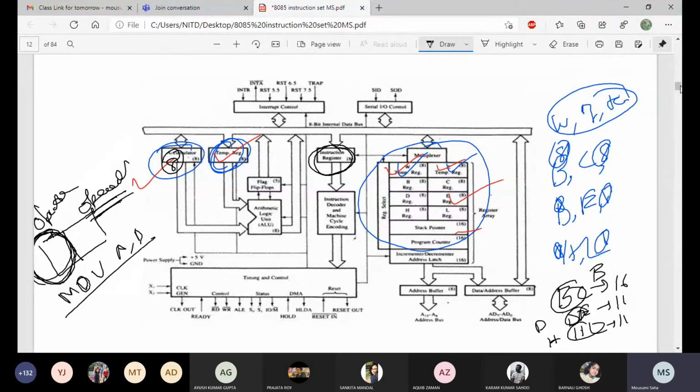This is the instruction, and I forget the opcode. This is the 8-bit code. Suppose XX is the opcode, and the operands are A and B. Whatever it is, for this instruction only one opcode is sufficient. It doesn't need any operands, because the instruction gives the information of the operands, and those are all internal components of the processor. At that moment it has only the 8-bit opcode.